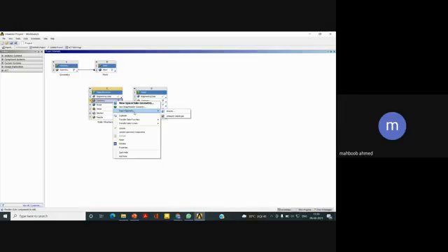You can import the geometry that you have earlier made in other software like AutoCAD, CATIA, ProE or SolidWorks. There is some requirement for that: the file format to import the geometry here is in general IGS or IGES. If you have created your geometry on some other platform, you have to convert it into a specific format, and it accepts IGS and IGES format.